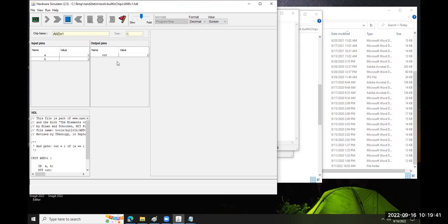And so, let's make sure it's really working like an AND. If I change the input of the A pin to false, when I run it again, what should happen to the output value? 0. It's going to flip back to 0. Yeah, thank you. So it flips back to 0. So I have a way of validating that that change did not cause a problem.